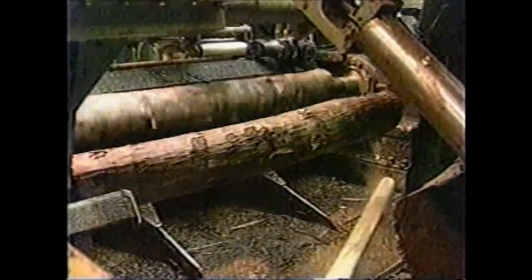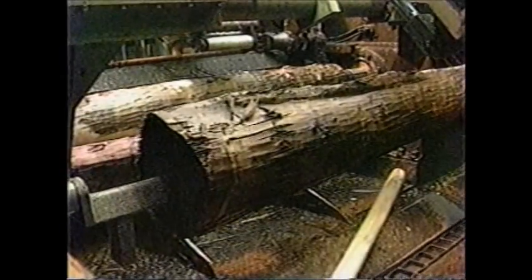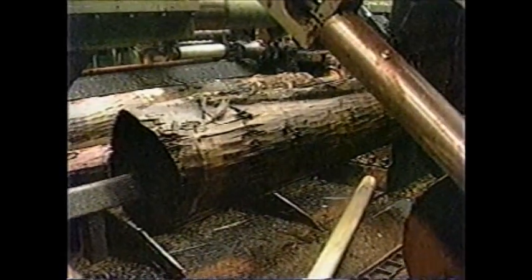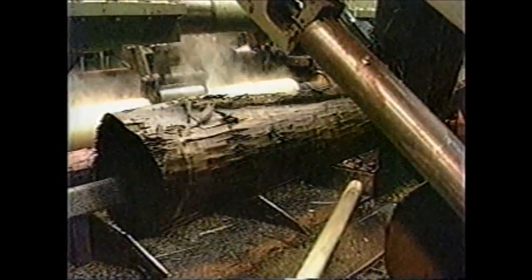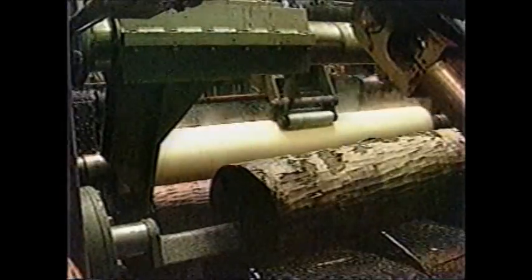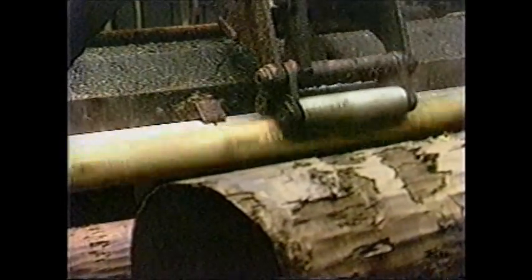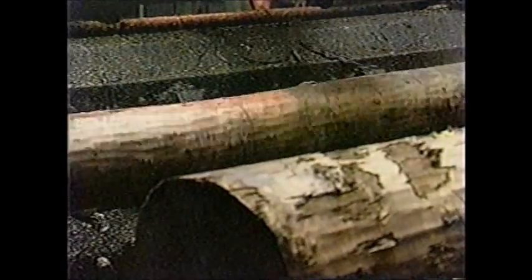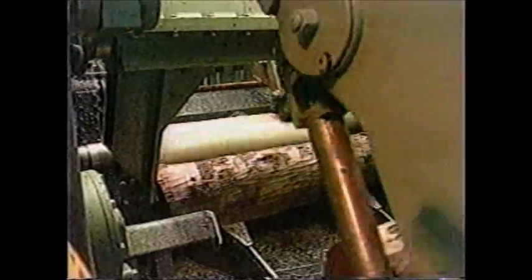The bolt is then passed to the lathe, where chucks grip the bolt ends and transmit torque to turn the bolt against the lathe knife. As the bolt revolves against the knife, it is automatically fed into the knife to produce a continuous ribbon of veneer. As the bolt is reduced in diameter, a backup roll is lowered to the back of the bolt to stabilize it. When the bolt diameter has decreased to about 5 inches, the core is automatically ejected and the next bolt is brought up.